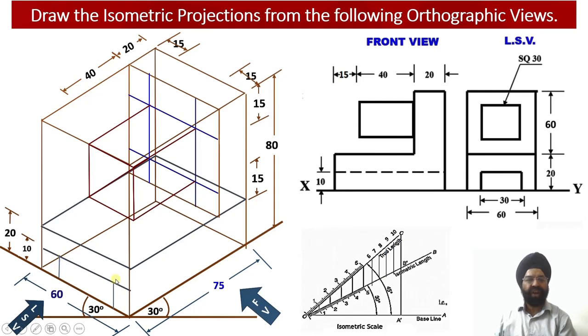Now this construction of the slot is also completed, and then this is the back side. This is the bottom portion as the slot is going to extend till the end. So this is the bottom line which will be visible over here. This is the bottom edge of the slot which will be visible. So even the bottom edge goes like this, but since this is covered by this vertical leg of this lower web over here, we have not shown this particular dotted line, because in isometric projections we are not going to use any of the dotted lines over there.